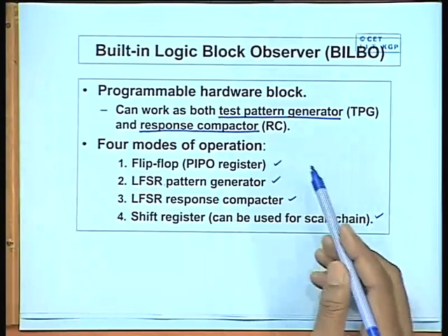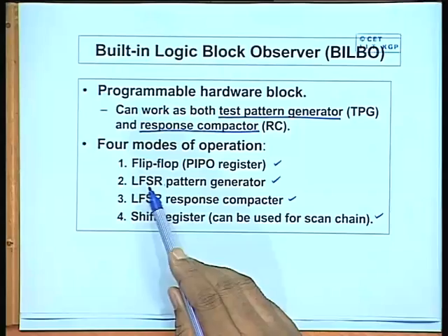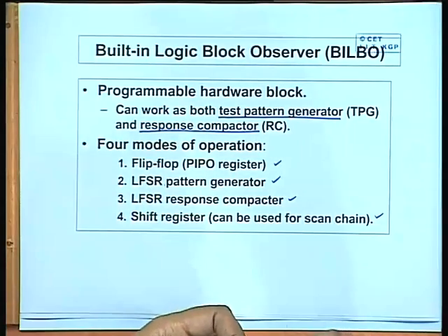Okay. Now, just one thing I would like to mention before I proceed further is that we are talking about an LFSR based pattern generator, or on chip pattern generator. But usually, the patterns that are generated are not exactly the type of patterns generated by a test generator program which we had discussed earlier. Rather, a special hardware circuit is used which can generate very good pseudo random patterns.